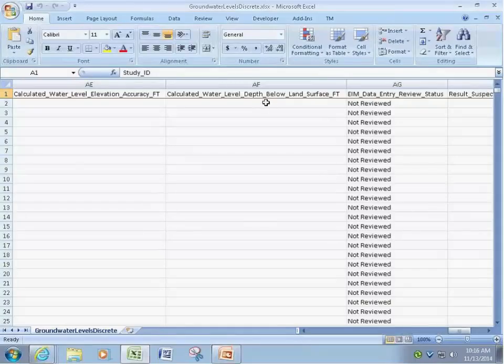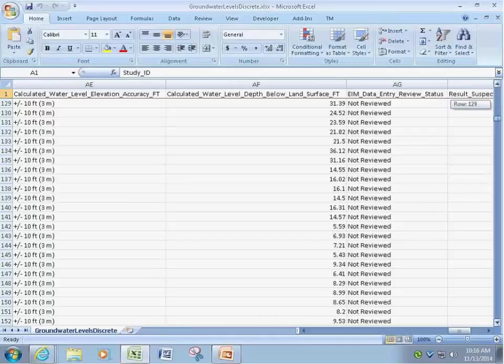That's because it doesn't have the metadata that the system needs to normalize water levels as depths below land surface. In this case, it would be the stick up on the casing that is missing. Other wells do. So you'll see this mix and match of complete metadata and incomplete metadata, but where the metadata exists, you should get those normalized values, and that's our goal.